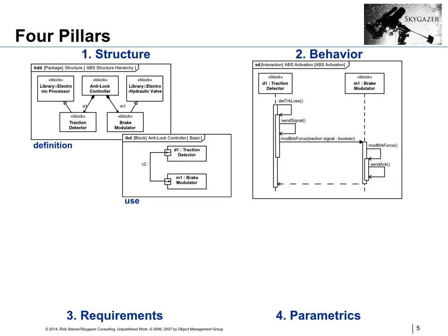One way that behavior can be represented in SysML, we get this directly from UML, is the idea of an interaction or a sequence diagram. Sequence diagrams will be able to lay elements of structure onto a set of what are called lifelines, these dashed lines that go down the page when you're looking at a sequence diagram.